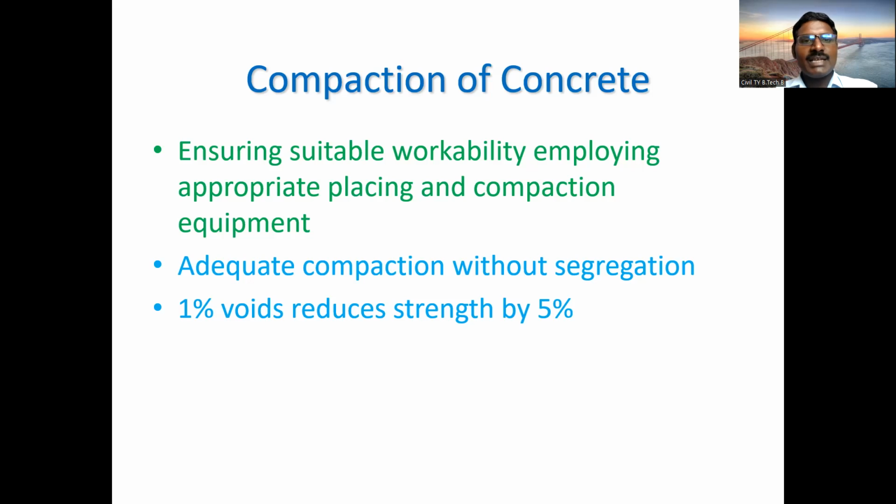We have to ensure suitable workability, employing appropriate placing and compaction. So adequate compaction without segregation. If we do more compaction, then segregation will occur, so without segregation you have to do adequate compaction. Again, 1% of voids reduces the strength by 5%.